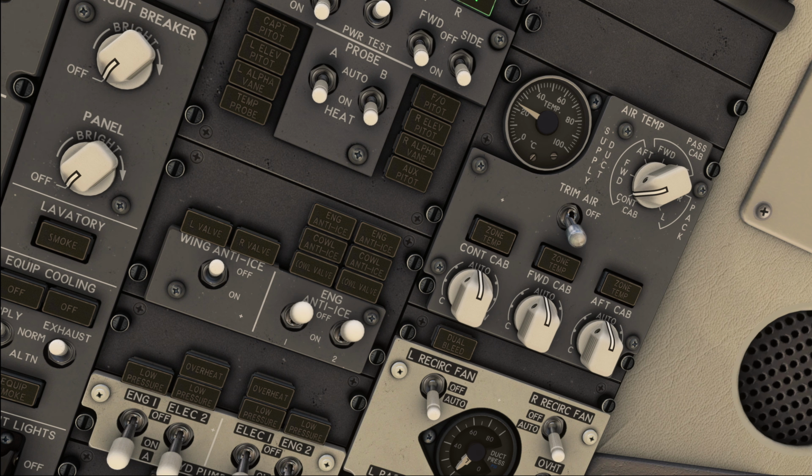The engine core anti-ice system is one that we need to talk about because it didn't exist on the 737 NG. Basically, due to the new engine, a new anti-icing system has been introduced that anti-ices the core of the engine, and this is called, well, the core anti-ice. Now, this system is fully automated by the electronic engine control and will turn on and off automatically without flight crew input or indication of normal system operation.